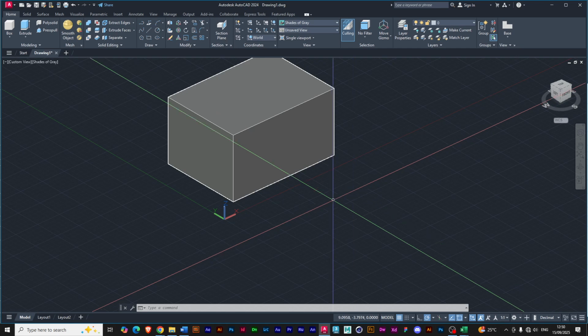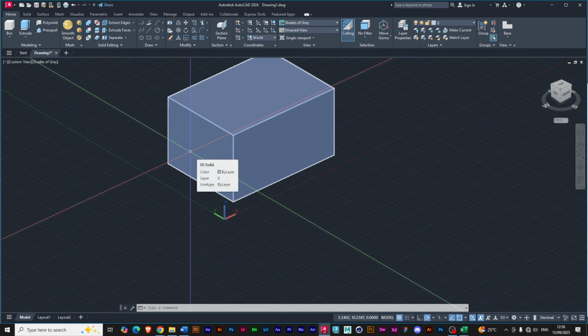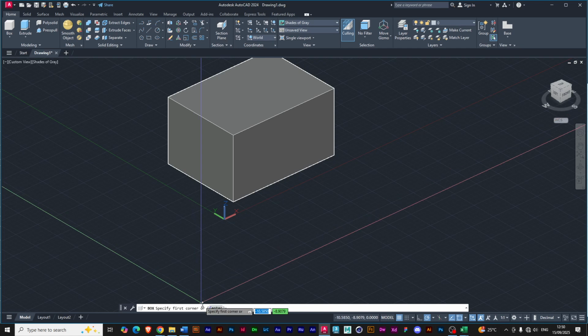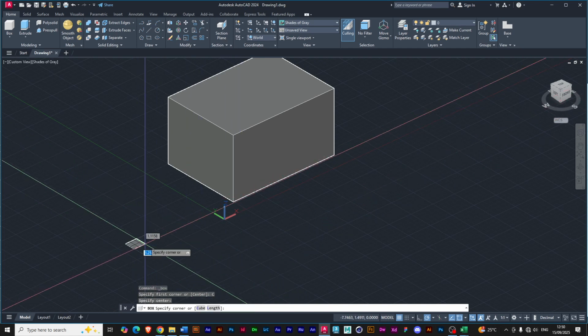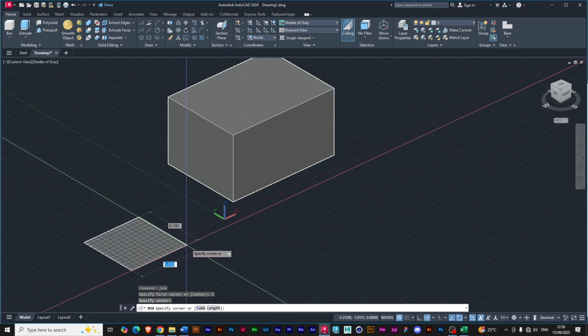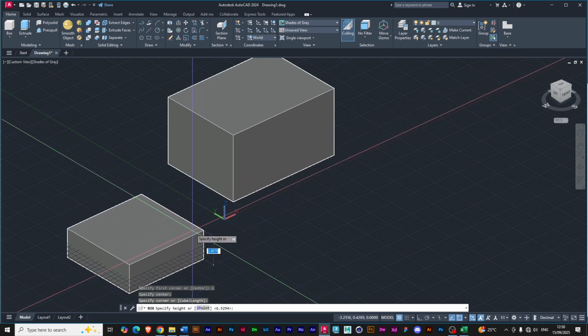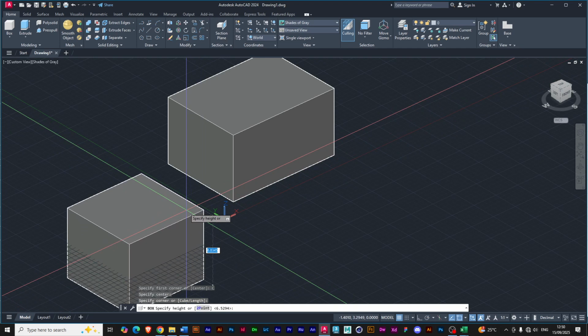Okay. So that is using the basic drawing one. But if I click that and use center instead, once I click and drag, it's going to draw from the center. Then I can now specify a corner before that center, and now the height is also from the center.